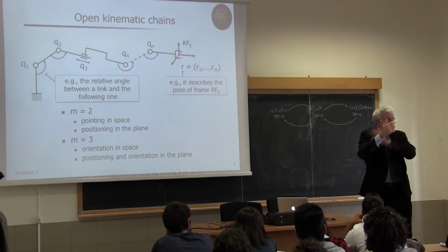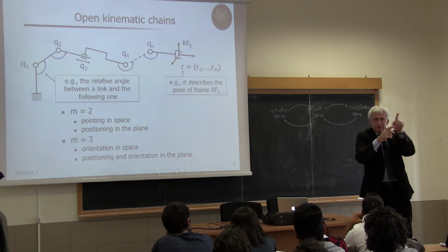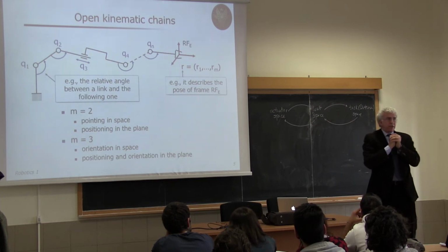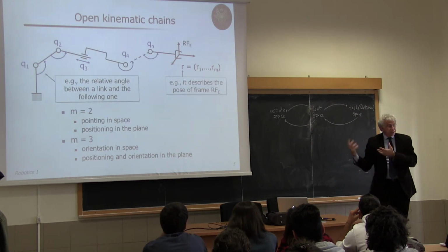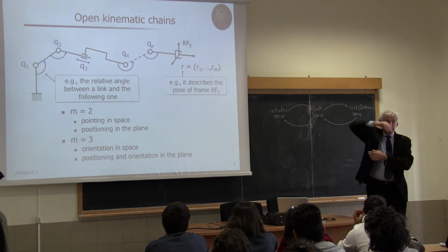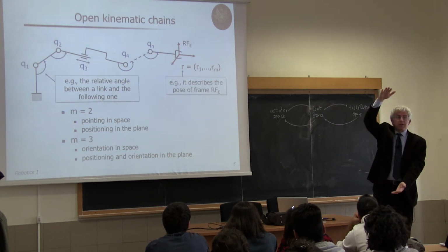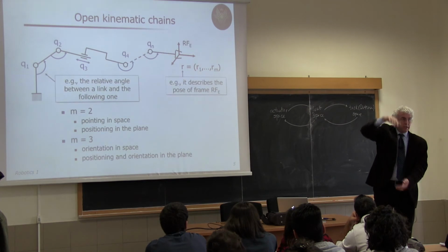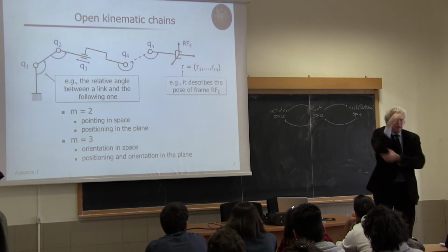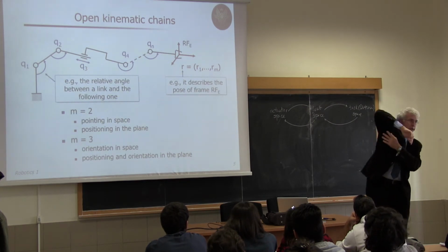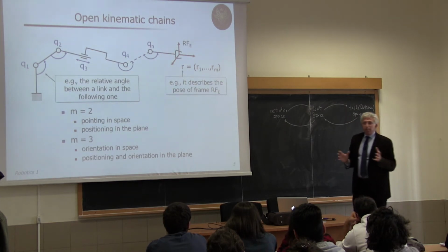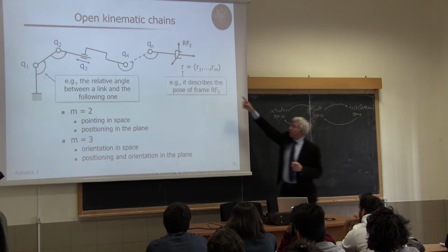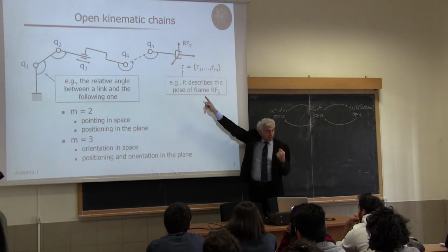This is possible because, once I have specified the pose of the end effector, I still have some degree of freedom. In fact, I have 7 joints. So I can specify that the elevation, just the y or the z coordinate of the elbow, should be here or here or here. So I have 7 variables for describing the r vector of my task.